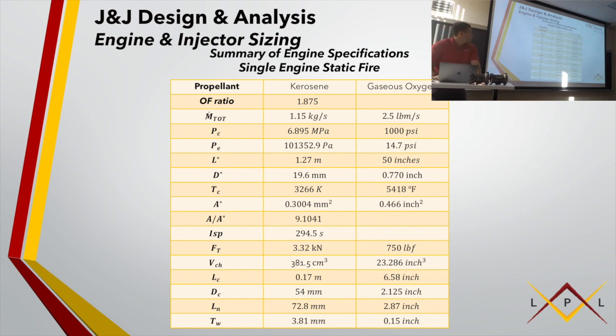But if you were at a company like SpaceX, for instance, for Raptor, this changes all the time, because you pick a design point, and then you're like, all right, everyone, this is what we're operating at. This is what it needs to be in the chamber. This is the pressure you need to give to me. And then someone's working on the pump, and it's like, damn, you want that high of a pressure, and you're starting at that low of a pressure. I'm going to have a ton of cavitation, or I'm going to need a multi-stage pump to generate that sort of pressure that you want, right? Because, for instance, Elon wants 300 bar in the chamber, which, like, what's 300 bar?